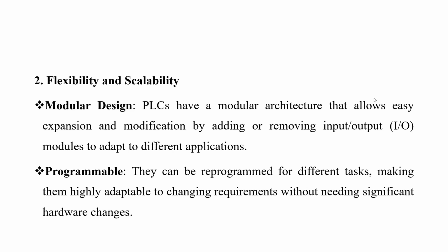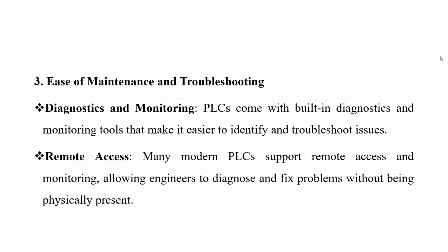So we also find that they are flexible and scalable. When you look at the modular design of PLCs, you have a PLC that is playing a function today, but it has the capacity to expand. There is that possibility of expandability, of expansion. So you can either add or remove the input-output modules so that you adapt to different applications. They are also programmable, so that makes them flexible, meaning you can write another program from what it previously was operating on. You reprogram it so that it can now play a function in a new application.